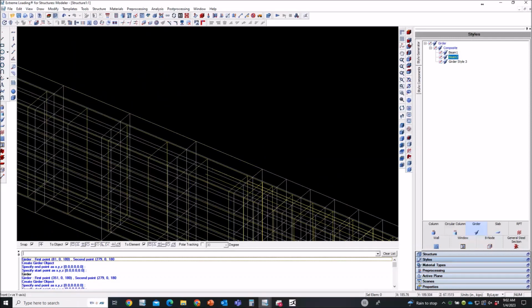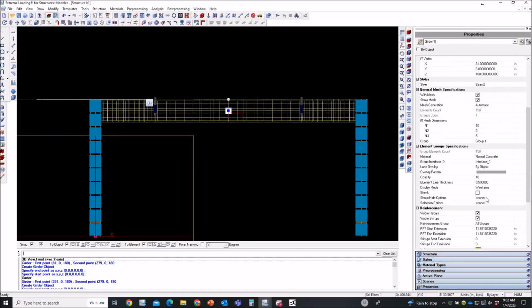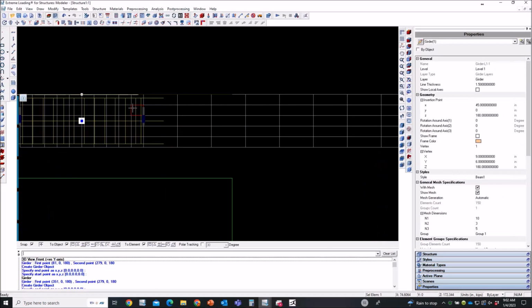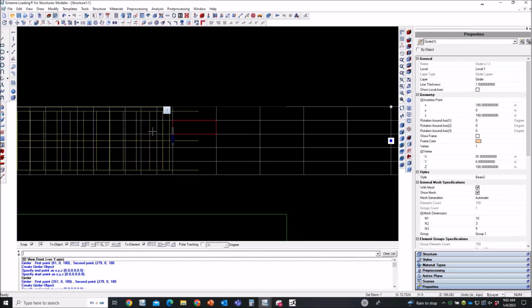Now let's stop here for a few seconds and try to figure out about the extension of the reinforcement. I will just go ahead and close here the reinforcement bars. I will just hide them to be able to explain what we are going to do. So basically, at this surface or at this interface between beam number 1 and beam number 2, I only need continuity of the bars. I don't need to duplicate the bars coming from this beam to this beam.